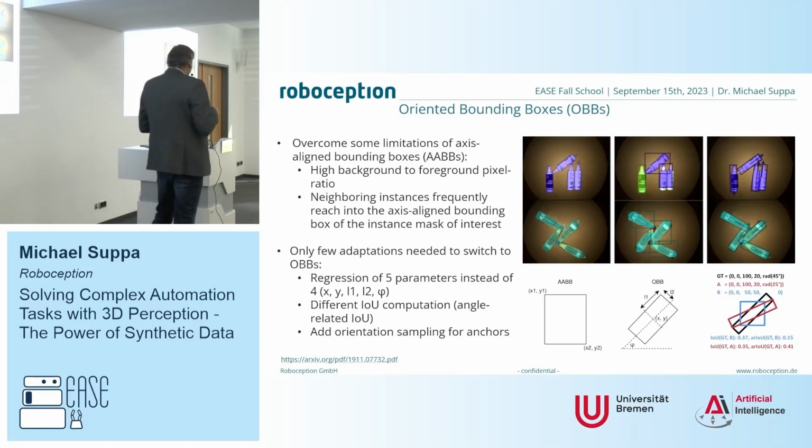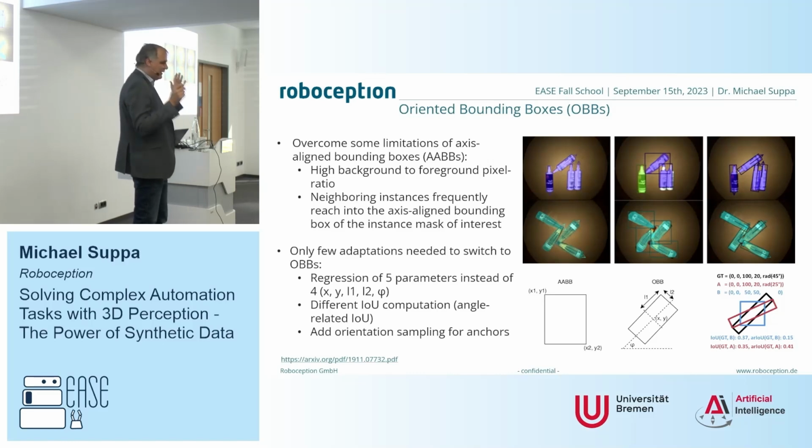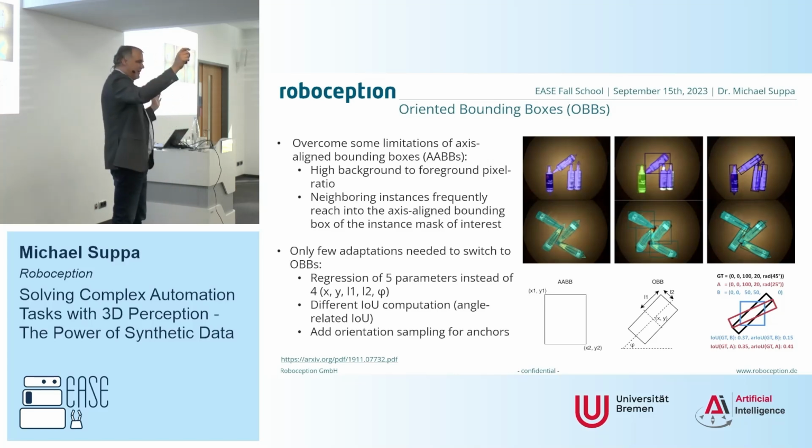You can see that from left to right. So this is the scenario that we are having. And here you have the issue with the axis-aligned bounding boxes, because these are the scenarios that we see most of the time. Objects are never separated. If they come from the bin or from the stack, they usually do overlap. And then, of course, it helps a lot to have an oriented bounding box here and work with that. Also, there are some issues when objects are very long, especially when they come from the bin. Usually people say, you know, there's a stick in a bin, that's a simple part that's easy to grasp. But if you deal with a bounding box detector, it's really bad, because it may span a large area of the image, and you have so many items in that.